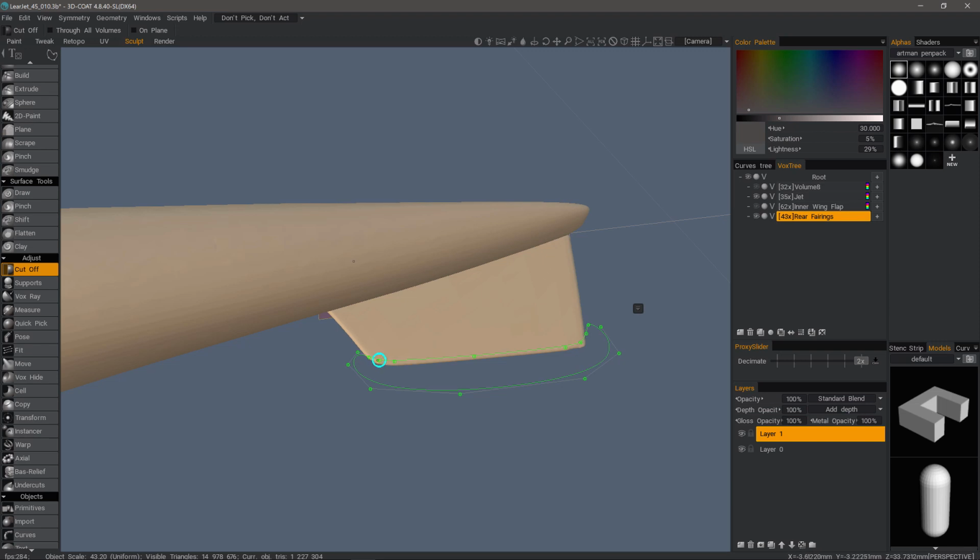I can hover over any one of these and edit them after the fact. You have this little toggle that gives you options. You can detach it from the surface, you can make it attached to the surface and so on, but I'm not going to go too far into that. One thing to note is when you're using a spline, we need to hit the Enter key in order to apply it. So I've done that. I can save the spline for later use if I need by going here and choosing Save and then load it later. All right, I'll go ahead and hit Escape.